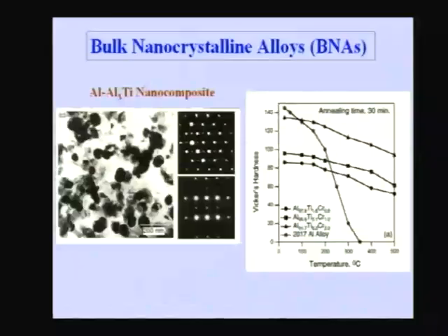So extra lines are visible from that only, we can say? Yes, from the extra lines one can see, but the important thing is that the extra lines are so faint that in some cases you may not even see them. For example, take copper zinc, a typical example of brass; we all talk about beta brass. Beta brass can be ordered at temperatures below around 550 degrees or so. Below 550, you usually have an ordered BCC structure, which is beta prime, or beta dash, as people call it, and at higher temperature, you talk of a disordered structure.